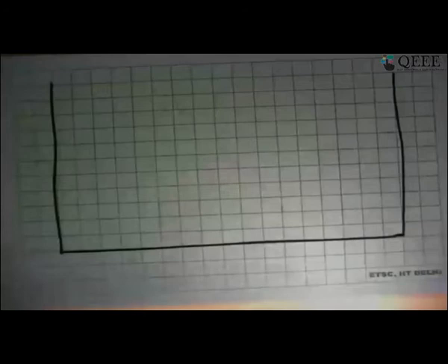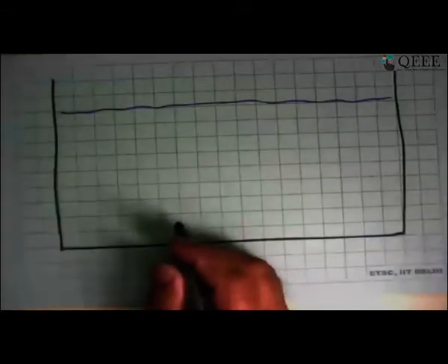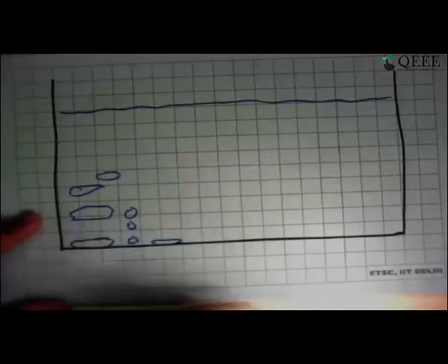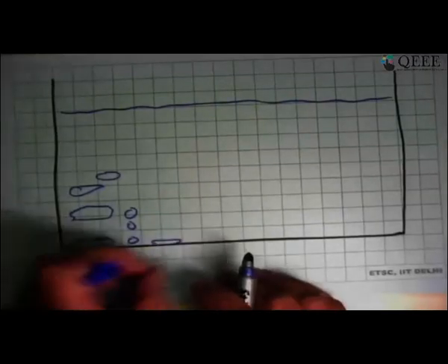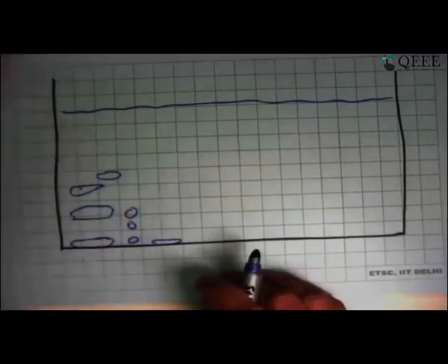That's the surface, and we have here the liquid free surface over there. And what we are saying is now happening is that in the initial part of this curve, here is what was happening, that you formed a vapor film there, but here there were bubbles rising there. This film would break up and then start moving up, and maybe it may further break up into pieces, and this will go up. And as soon as this detaches, another amount of liquid comes in contact with the surface, and again it begins to form a film. So this part of the surface gets a smaller film, gets a bigger film, it breaks up and goes up. Another film is formed. So that's the transitory nature.